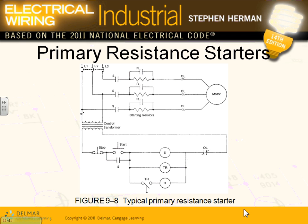High voltage drop as you start the motors. Certain motors might not start. If you have 50 motors starting at the same time, you wouldn't have enough voltage to start all of them. So that's electrical stress. The second thing is mechanical stress. High starting current will create a high starting torque. Imagine you want to smoothly move something on a conveyor, and instead it jerks. When you start, it pulls that conveyor and things will fly all over.